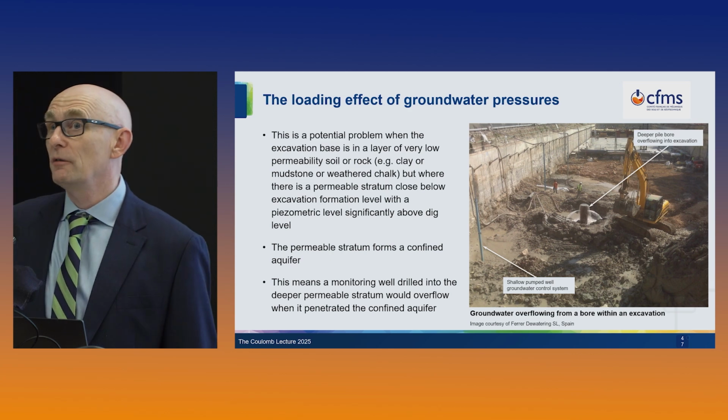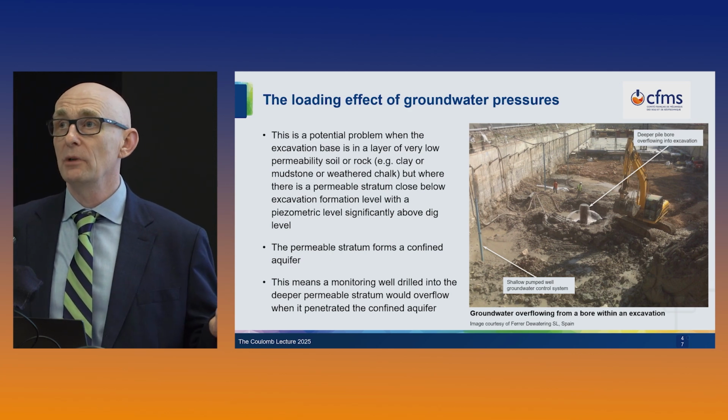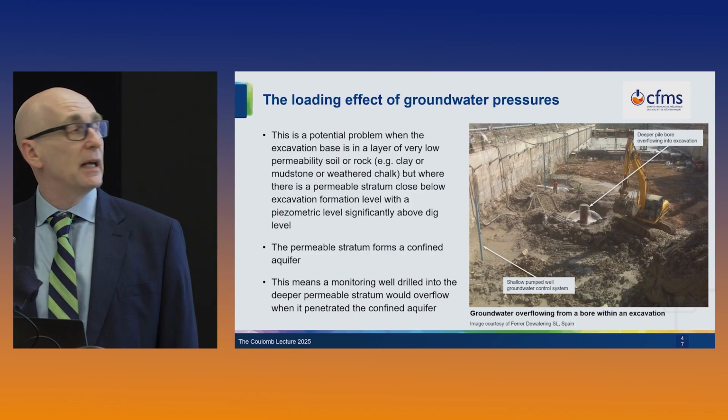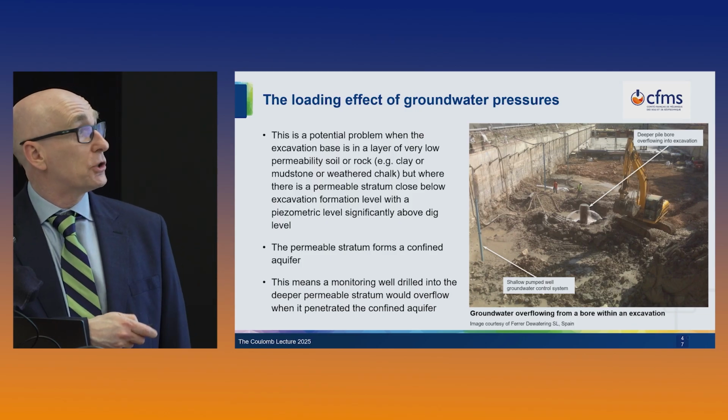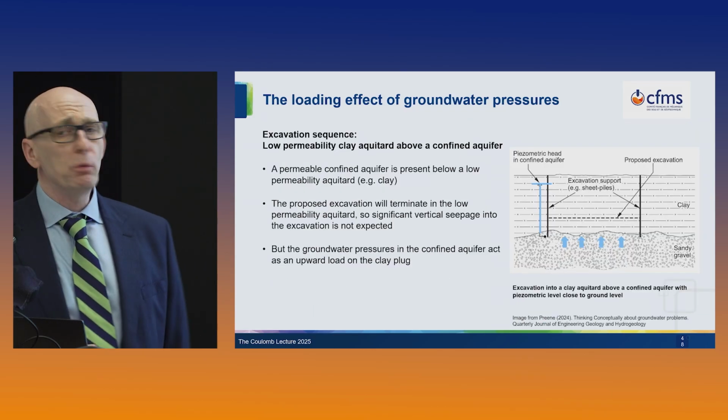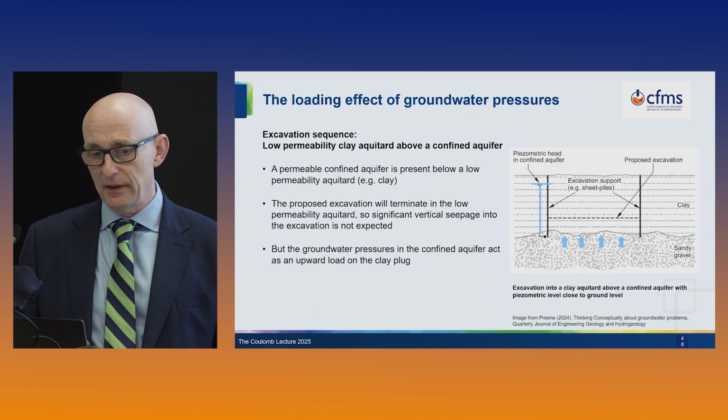It's probably good that it's overflowing because this will be acting as an inadvertent relief well, reducing the pore water pressures. But you can see that this does happen. And I could give you many examples where this hasn't been discovered until the excavation actually has failed. And how would a failure occur? So let's look at a sequence of excavation.